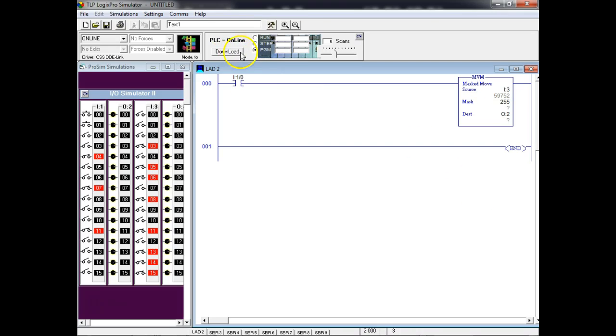Yeah, I used an output port that didn't have anything in it. So here's all these guys. Bit 15 was set, but it came up cleared, right? Bit 14 was set, it came up cleared. Bit 13 was set, it came up cleared. When I got down below here, this is 1. It's true. This went true. This is true. This went true. This is 0. This went 0. Y'all see what I'm saying?